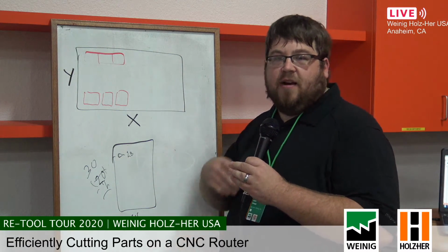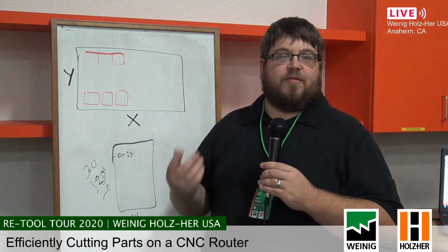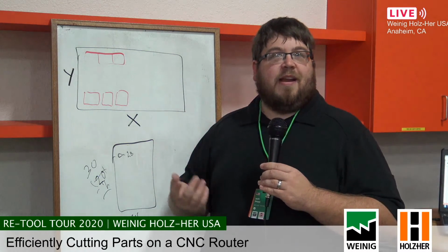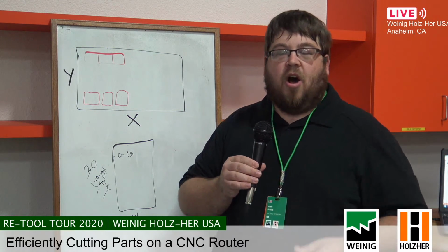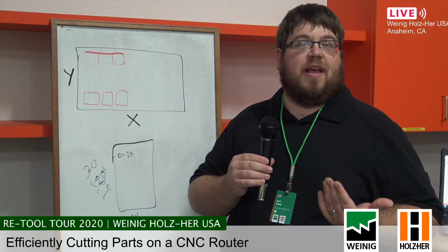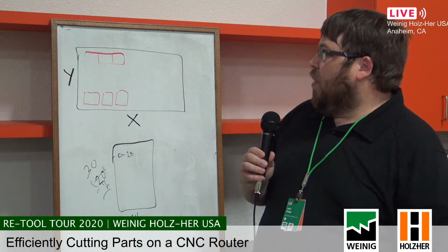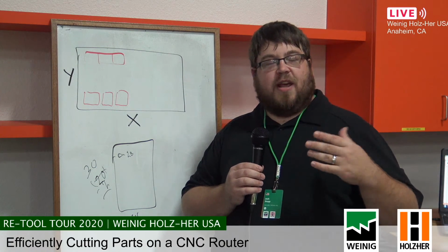And all that is done automatically. There's nothing on the user side of it that has to dictate how that's done. You simply tell it, I want to do this common line or I want to do it conventional whenever you're designing the part. And so upon doing that, you can get much faster nesting times and actually get faster production out of the same machine versus doing it conventionally. Also, there will be a little bit less tool wear because you're not going back and forth in the same spot.